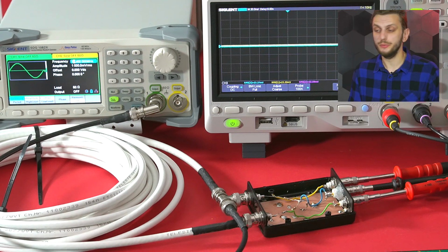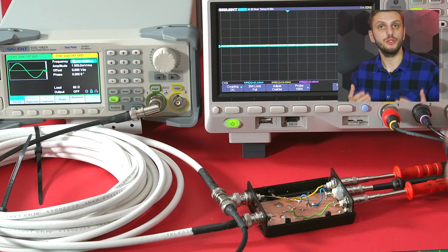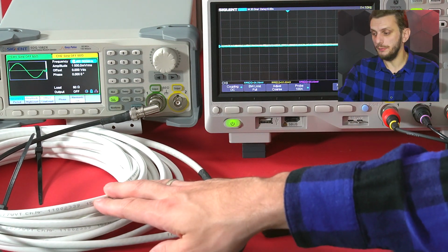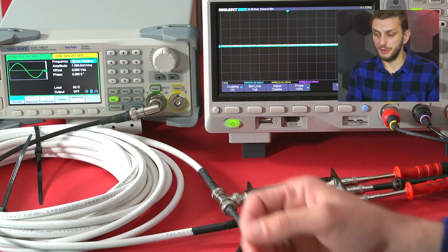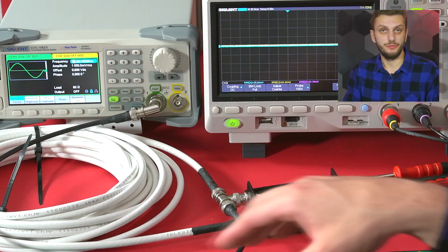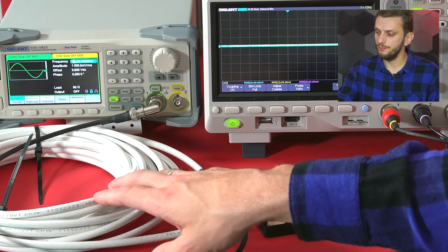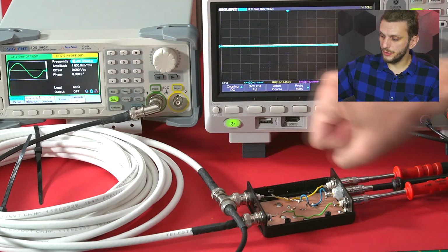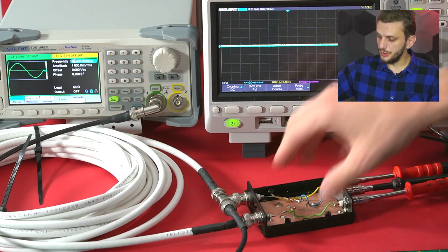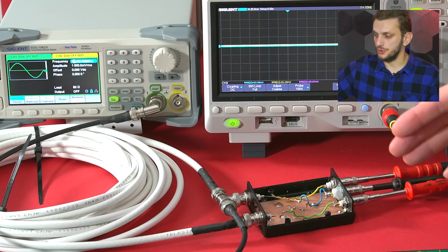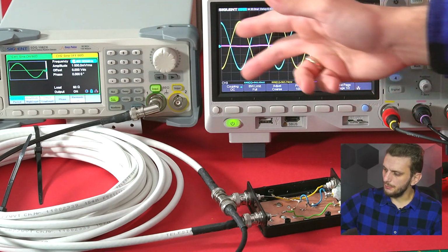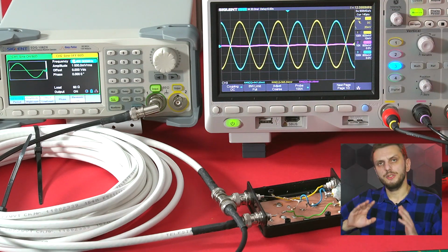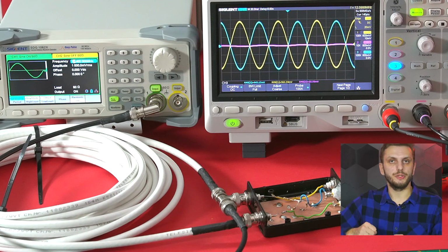So first thing to play around with is the half wavelength 1-to-4 balun, and I built this with about 10 meters of 75 ohm cable. The impedance of this cable should not really matter, everything else is 50 ohm cable, just this is 75, and for this I connected one side to the signal generator and the other to a 200 ohm load, and I'm measuring this using 3 channels of the oscilloscope. So what we will be seeing are the 2 branches of the termination as well as the ground current. So let's now look at the various measurements in a bit more detail.